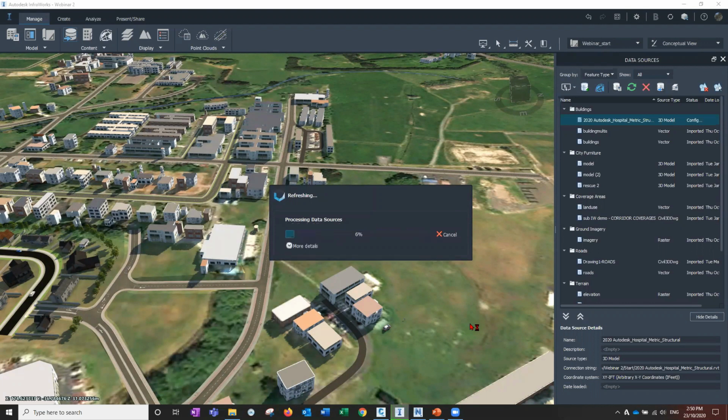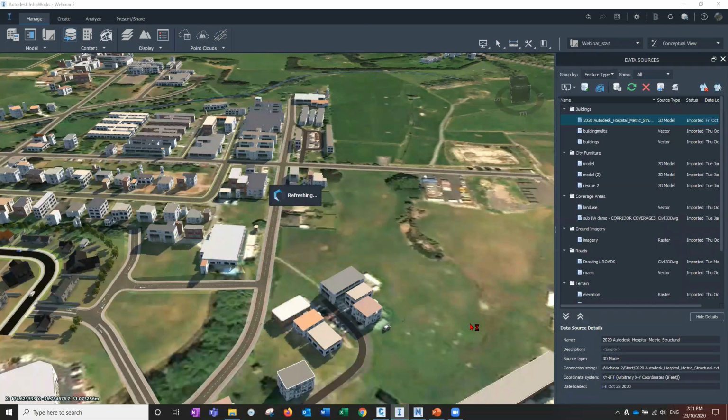Hopefully everything's up the right way when we do it. Sometimes the origins, well, not origins usually okay in Revit, isn't being up the right way. With things like Inventor, sometimes the Z-axis is horizontal rather than vertical, but you've got that in the configuration settings. You can change those. And we can also bring in, if we get time, a Plant 3D model as well. Plant 3D is based on AutoCAD, so it comes in as an AutoCAD 3D model, like you read in an AutoCAD drawing.